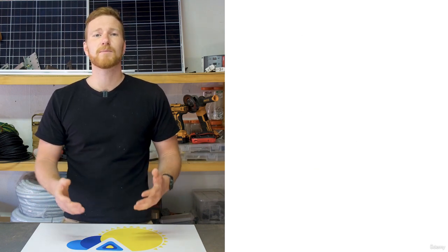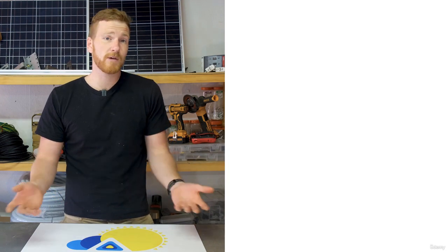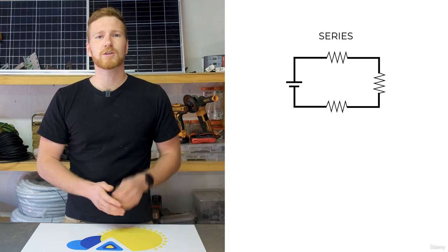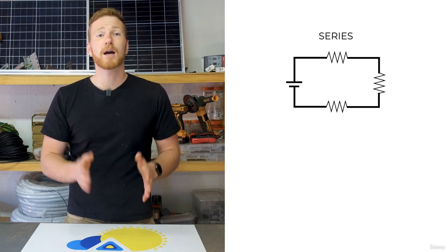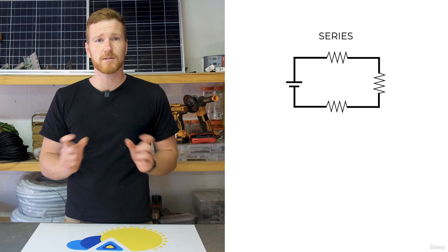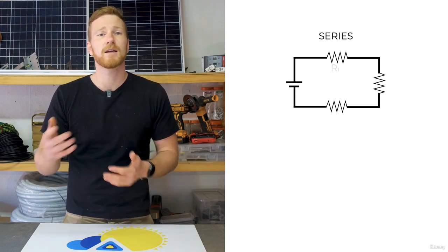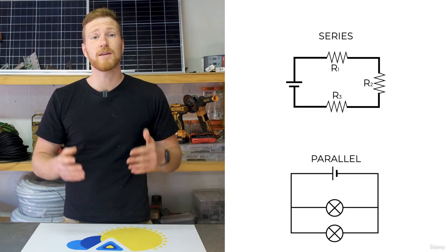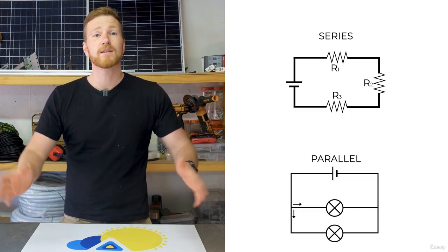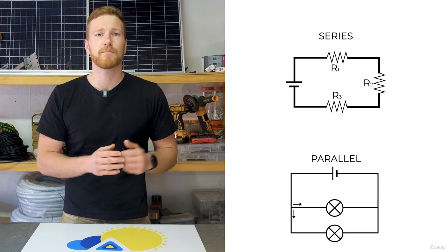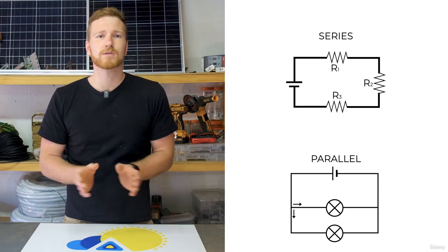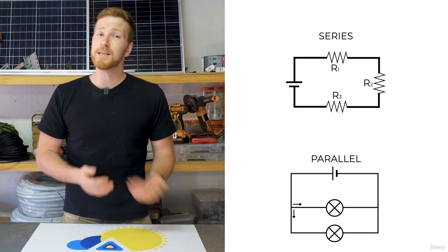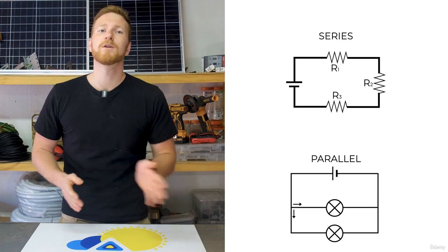Electrical components can be arranged in a circuit in the following ways. In series, this is where loads connect one after the other. Current and voltage will vary across the 2 loads or more, depending on their individual resistances. They can also be arranged in parallel, where there is a fork in the circuit where the same voltage will be applied on both components, but the current will also diverge according to their resistances, where the component with the least resistance will have more current flowing through it.